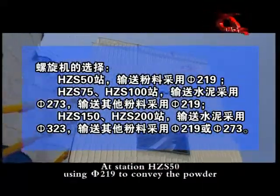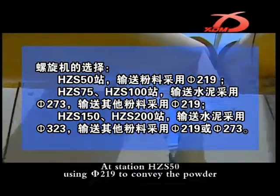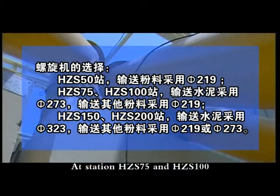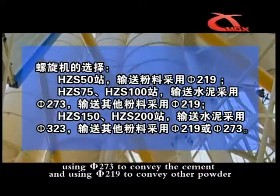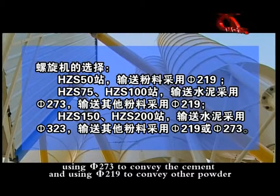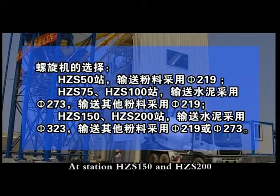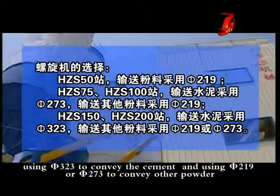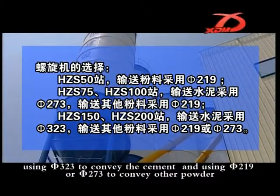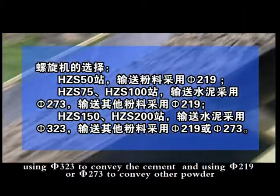Selection of the screw conveyor. At station HZS50, using diameter 219 to convey the powder. At station HZS75 and HZS100, using diameter 273 to convey the cement and using diameter 219 to convey other powder. At station HZS150 and HZS200, using diameter 323 to convey the cement and using diameters 219 or 273 to convey other powder.